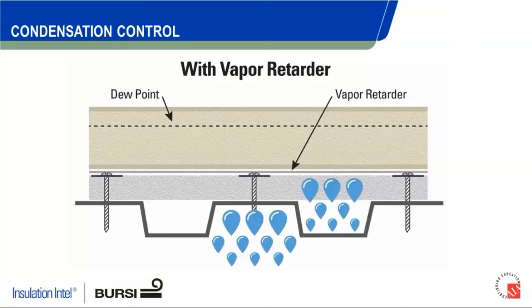That way you don't have penetrations in your vapor retarder, your vapor barrier, which can lead to it not performing to the full capacity that it can. So what you see here is one option, which I think is best practice for your steel decks.